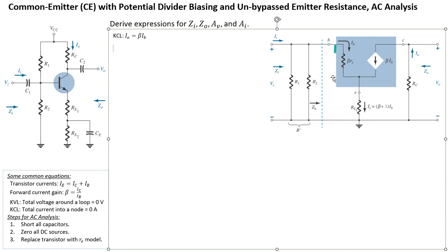That's the total voltage across from the top to the bottom, which is also called VI, by the way. It's the same node. But here we need to express it in terms of these two components. So we can think of it as the voltage across beta RE plus the voltage across RE1. So we do Ohm's law here, another Ohm's law here, and KVL for the two combined. So let's figure that out.